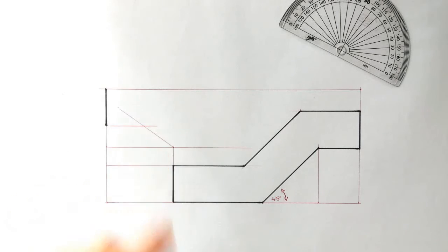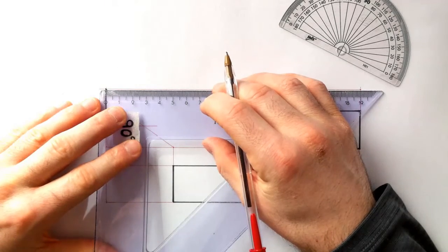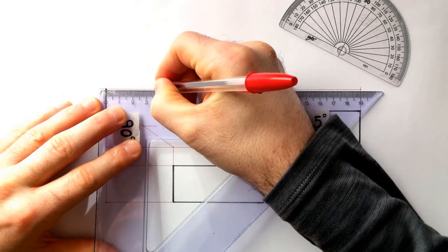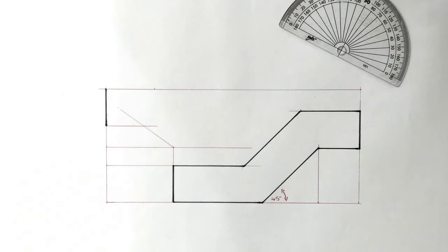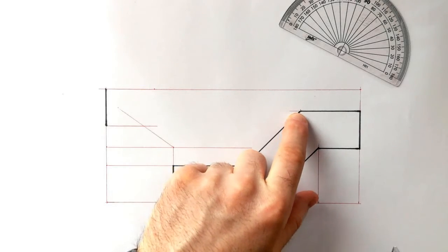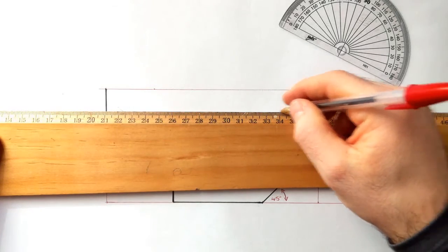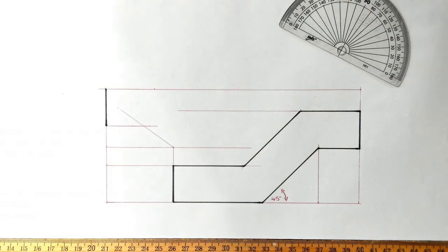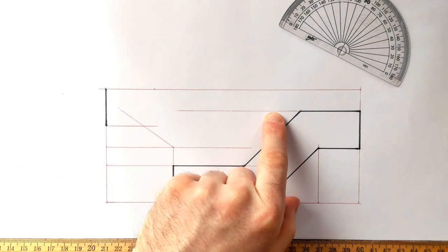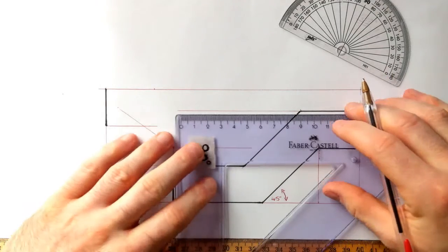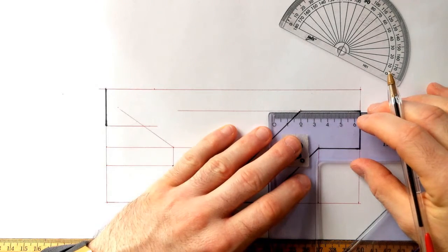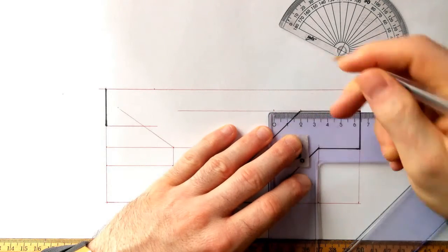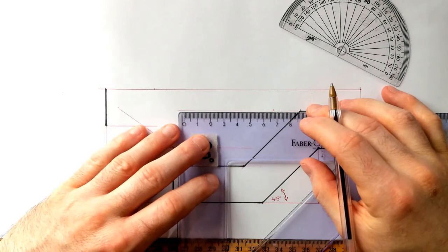Okay, now from up here it says it measures out 36 millimeters. So I'm going to measure out 36. So there's my little mark for the 36, and then also it tells us from here, and this is important, yeah, I need to extend my line on. Okay, construction line. It tells us to measure out 20, and then it also tells us to measure out 68. Okay, so I need 88 altogether. Just make sure I have enough. Yeah, I'm happy with that. So from that point that I previously measured, I'm going to measure out 20, and then from there I'm going to measure 68.